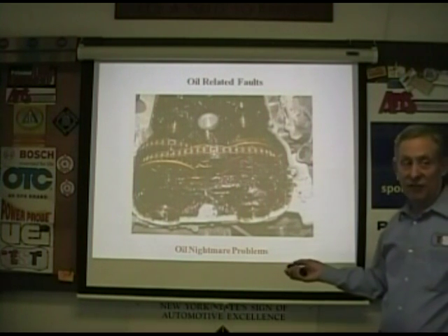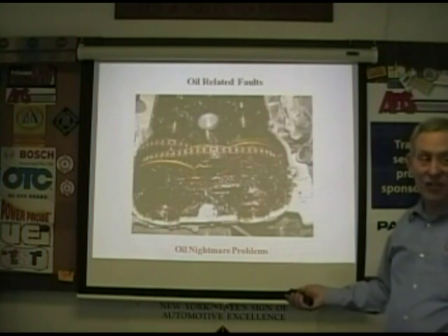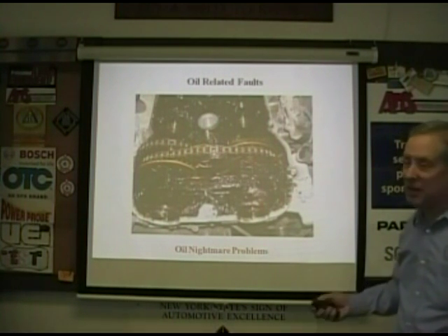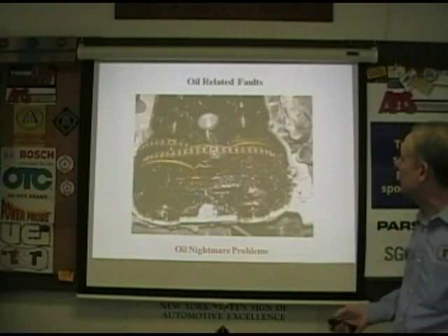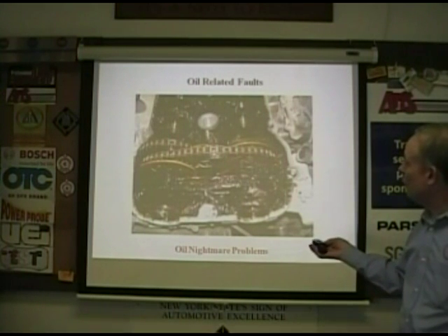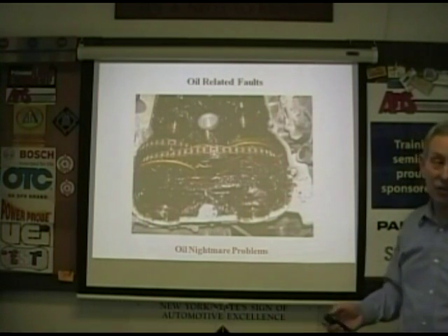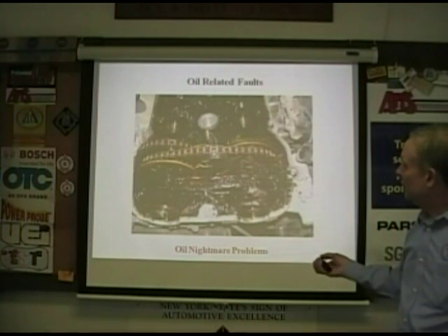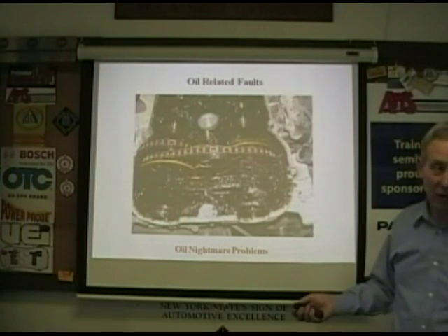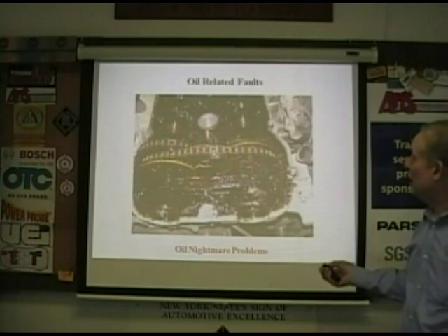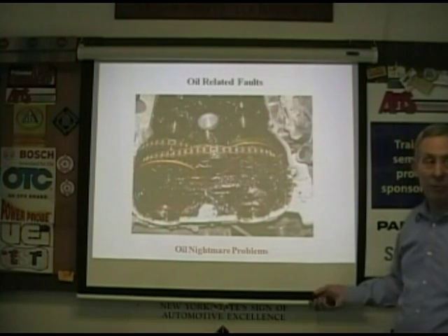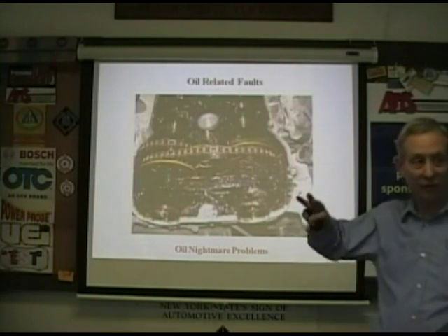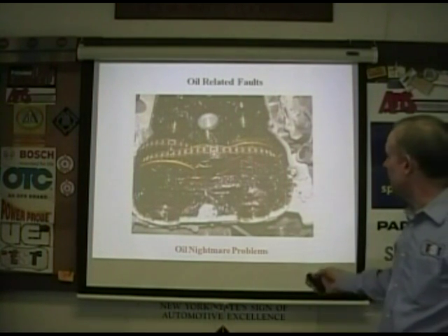There's actually a lot of different generations of Vanos. This particular Vanos, which would have been a mid-90s, late 90s version, would usually not actually chatter. What it would have, however, would be codes for cam advance. It might have a power problem. Sometimes they had a misfire problem if they hung in the other direction, in the advanced direction.